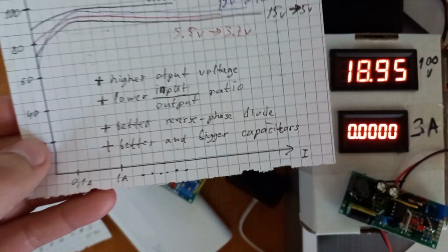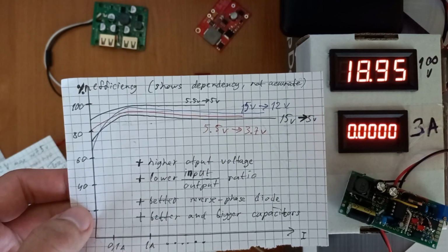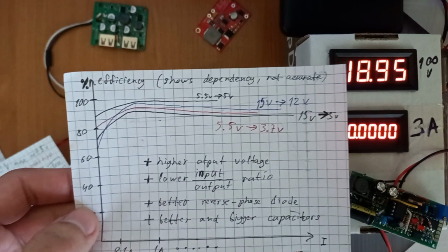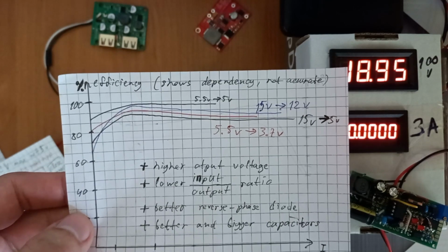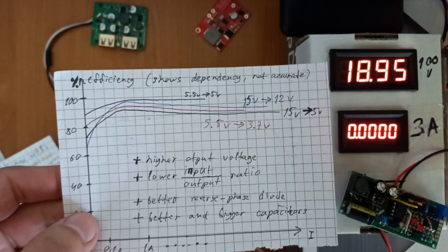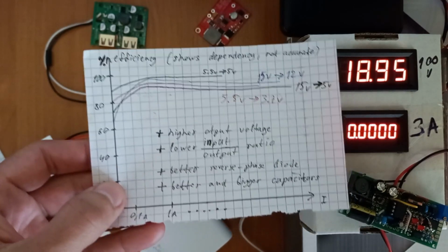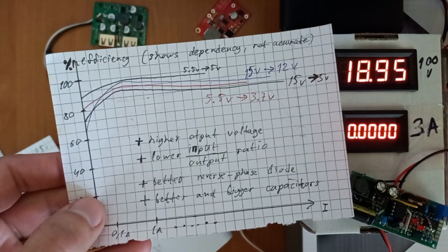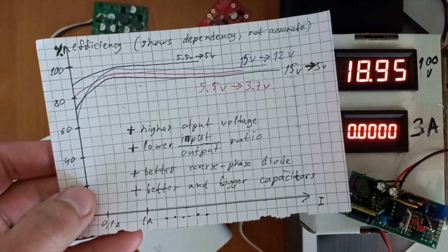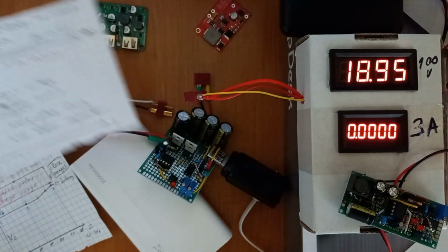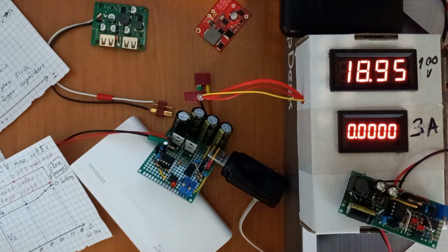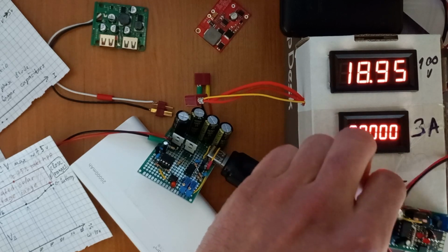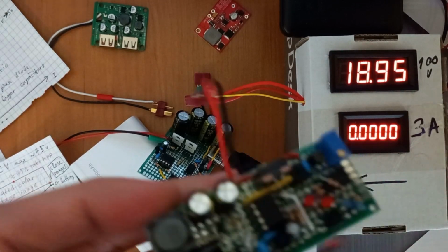When your output is some power bank, which has its own BMS, there will be additional internal losses of some 5 to 25%, which is a lot. So for an efficient solar power bank, this design needs to be custom, and you need to charge a battery directly without an excessive BMS that is oriented for USB input, like with this device.